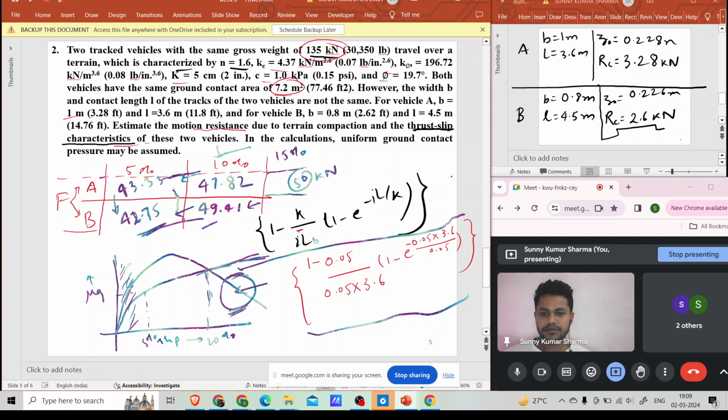Yes, sir. The power loss in the initial part is due to the force produced against the rolling resistance. The power loss at the end, which means after 20% slip, is due to the energy loss during the slip process.